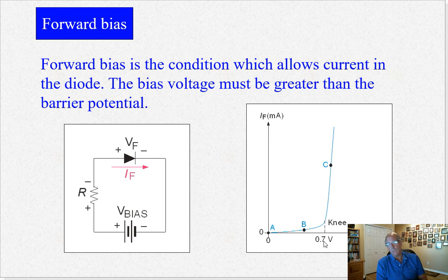But I've seen it even at room temperature at 0.6 volts, and some diodes like the 1N4001 diodes are like a full volt. Other diodes made of different materials like germanium, and something called a Schottky diode, are like 0.3 volts, much lower. They're very specialized diodes used, again, for power supplies, and they improve efficiency because there's less voltage lost across them.